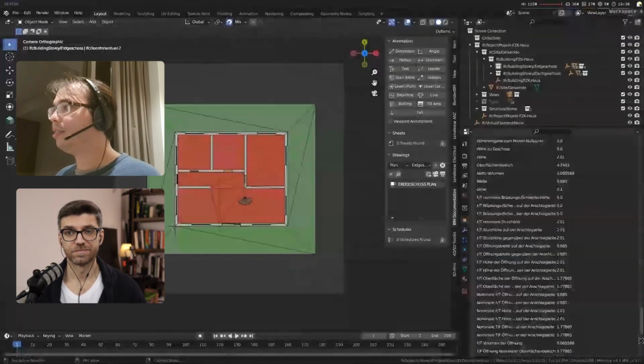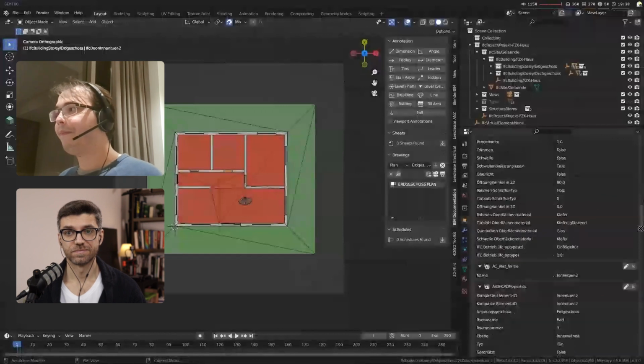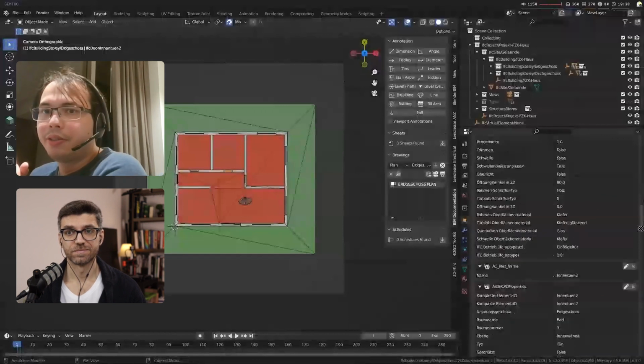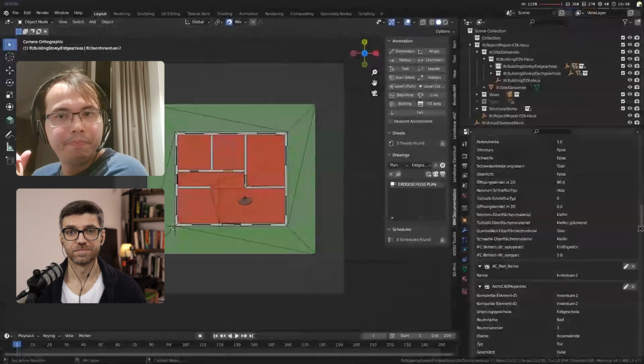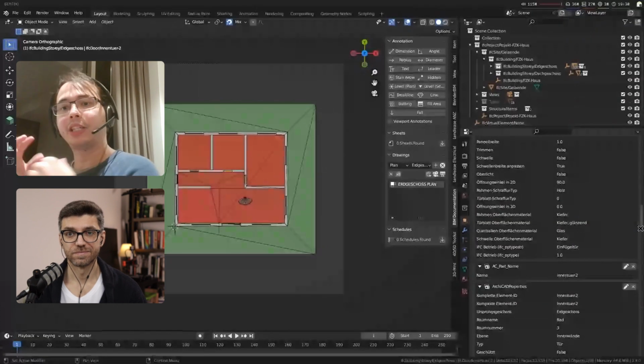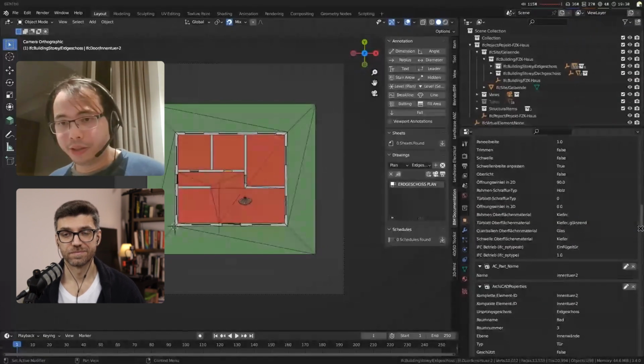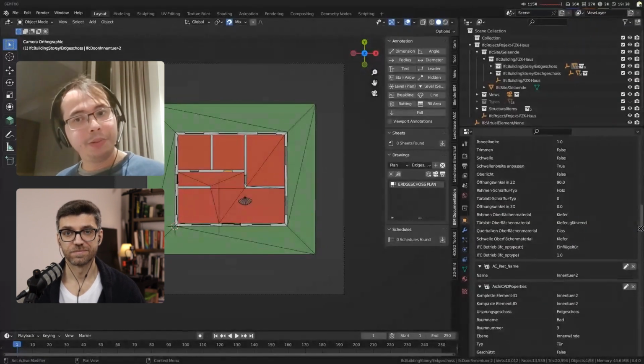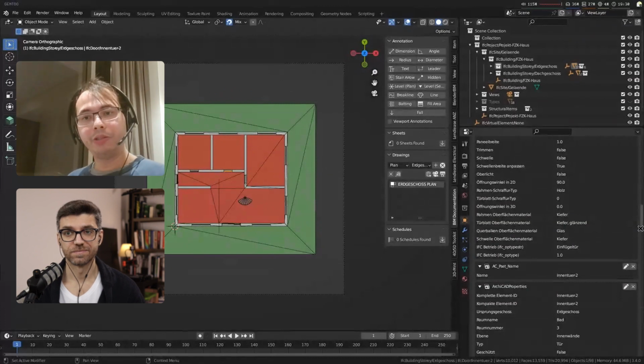And this is an interesting fact of IFC in that in traditional 3D packages, you have an object which has 3D geometry and that's it, end of story. Whereas in IFC, an object may have multiple geometries, because that's the way our industry works, right? A door might have one geometry in 3D, another geometry in 2D, another geometry for its clearance zone, and so on.